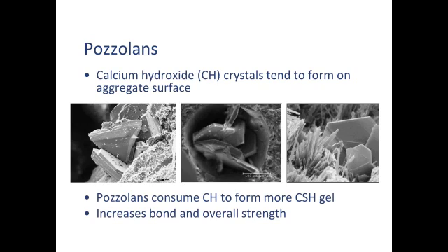These are scanning electron microscope photographs of calcium silicate hydrate crystals, and those are those big sort of really sharp, angular looking flat platey things. If you can see my mouse, that's some right there. And this is the outside of a tiny sand grain. This is a pore, an open bubble in the cement paste, and there's some calcium silicate hydrate crystals that have formed. 100 microns, if you could take a human hair and cut it in half, that's the width of a human hair right there, 100 microns.